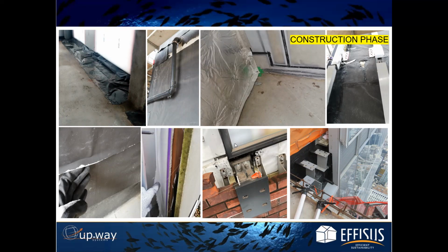Very commonly, site teams don't know exactly what type of accessories to use in different systems when they are applying both breather membranes and vapor membranes. Interfaces that are not well closed, poor perforation sealing, like I said, and this is all adding difficulties to the application.